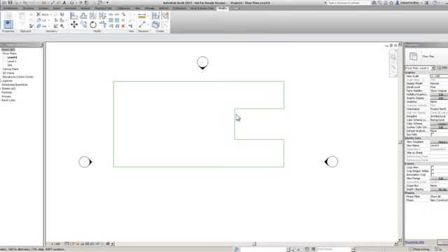Right, last couple of things. Curves, arcs, that kind of stuff. Obviously you saw us do the trim earlier on, trim and extend the corners, which is kind of replacing the fillet at a 0 radius in AutoCAD. Now what if we want to do a fillet but without just bringing it to a point at a 0 radius? What we can do is this.